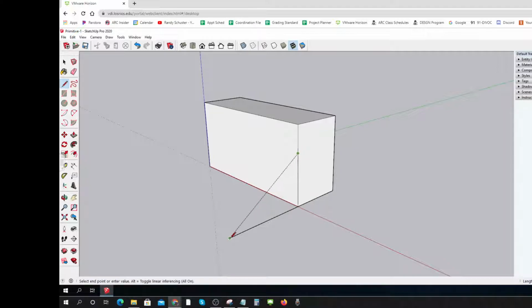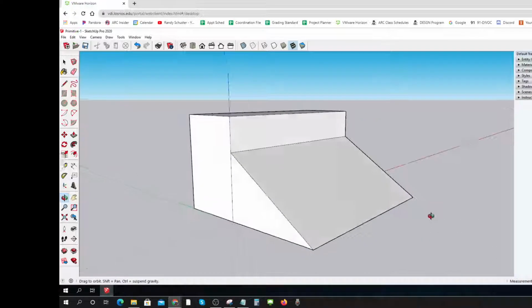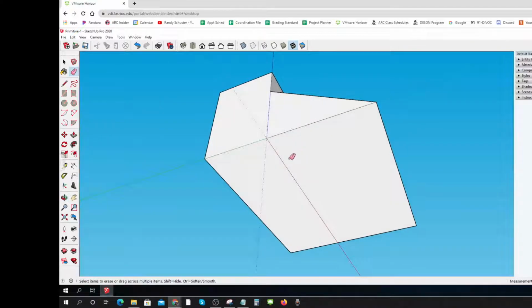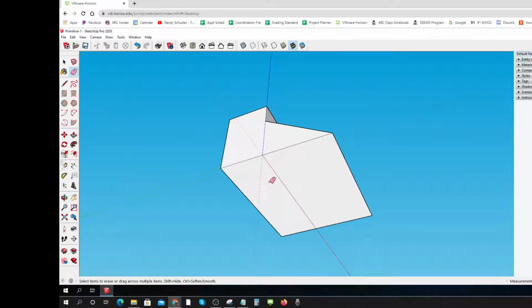And if I keep going up, bink, there's that little endpoint sign. Click and over to my other endpoint. And if it makes me a whole shape there, that's good. And now when I push-pull it, I know I can go 6, but I can also just go back until it hits the edge. There we go. I've got my first shape. That's really cool. If I want to make it really all one thing, I can get rid of that little piece. And remember, if I hold my mouse wheel down and I turn around, I can get rid of that little piece. And I'll bet you there's one on the bottom. And now I've gotten rid of all those things.